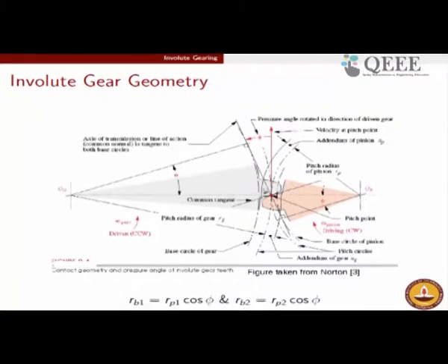The force that is being transmitted is in this direction. One component of it is towards the shaft direction, and the other component is perpendicular to the shaft. So, this component, which is vertically aligned and pointing in the red direction, is responsible for the torque. So, you take F cos phi, and this component gets multiplied with the radius and gives you the torque transmission.